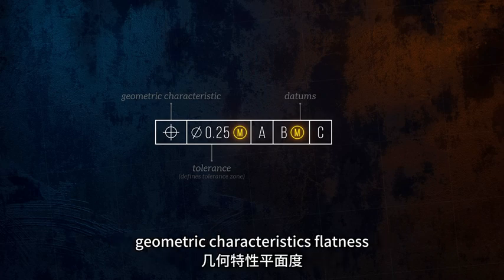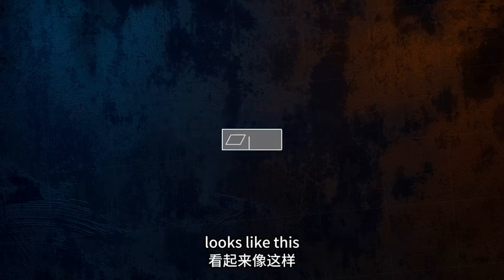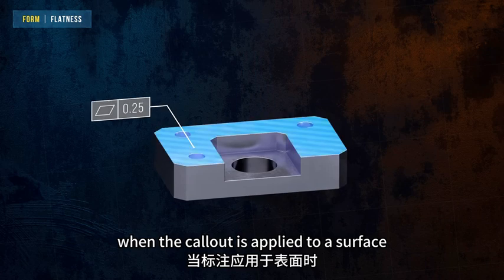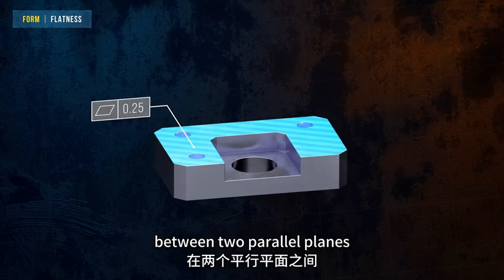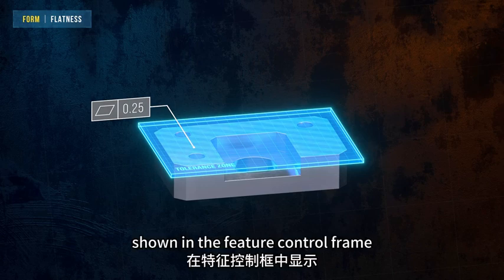starting with one of the simpler geometric characteristics, flatness. The feature control frame for a flatness callout looks like this. When the callout is applied to a surface, it defines a tolerance zone between two parallel planes that are separated by the distance shown in the feature control frame.